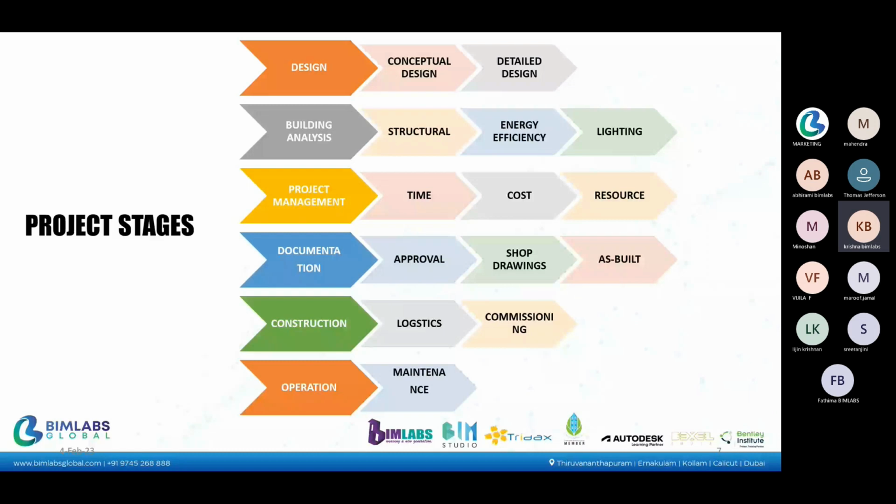Then as-built drawings. So we can say, if a picture can speak 1,000 words in a project, as-built drawings can speak 1,000 construction processes. That means it is a revised set of drawings. Even though we make all plans and do the construction, in the process of construction different changes will happen, isn't it? So we have to update everything in those drawings. That is as-built drawings. So as-built drawings reflect all the modifications made during the construction process.